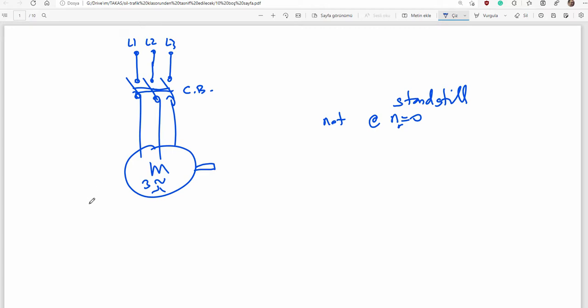You know that there is another port, magnetic field port in rotor. Here is the rotor circuitry. Let's write the terminals U1, V1, W1 for the three-phase AC connection. And then here are excitation terminals, which are F1 and F2. And you apply some external DC. Let's say here's a simple controller, RF field controller of motor.